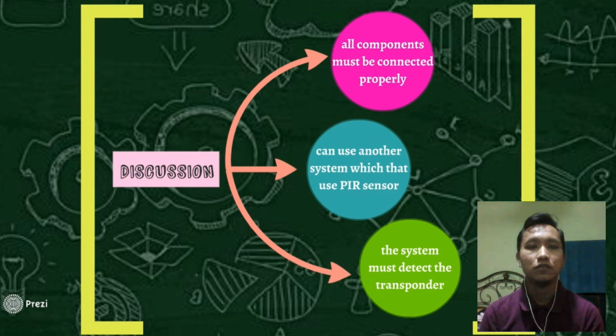The smart door lock control system can be placed into operation once all of the preceding procedures have been completed. When the right passcode is entered for the passcode method, the system will enable the user to access the room. If not, the user will be denied entry until they provide the right password. However, users can use another system, which is just using the PIR sensor. We just need to get closer and the door will be unlocked.